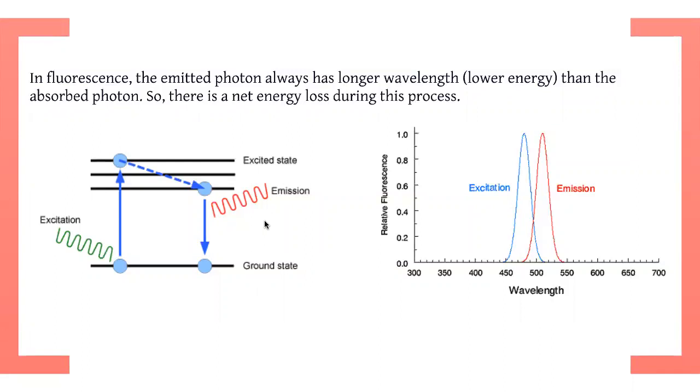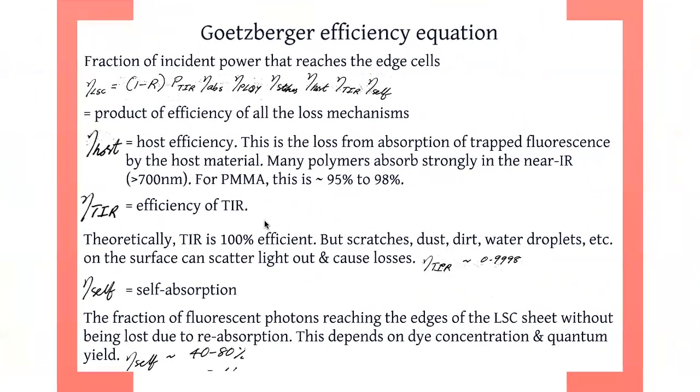No. Their band gap is always better for both. This is why the gallium arsenide cell, which has a direct band gap, gives you much higher efficiency because you don't need to match momentum. You automatically match the momentum because of minima and we are going a little bit off track. But I don't remember if Surangsu talked about this, but okay, so we can talk about it at the end. But a direct band gap material, so gallium arsenide, gallium nitride, for instance, is what's used in LEDs, right? Because the direct band gap material. Okay, so we're going a little bit off topic here.